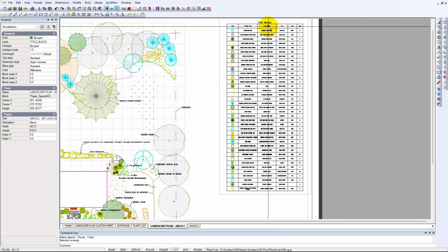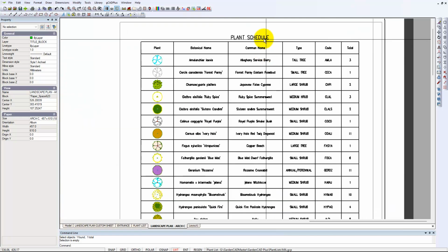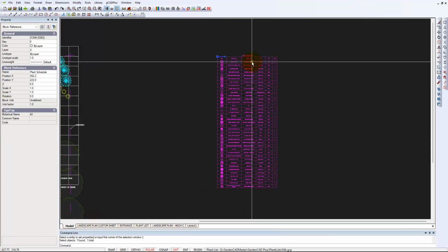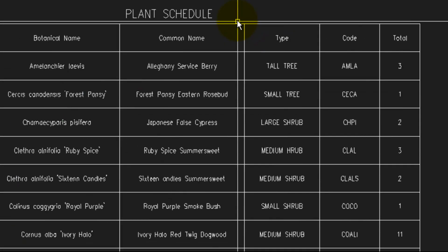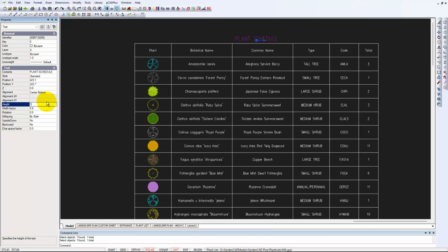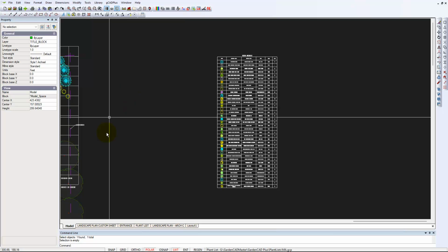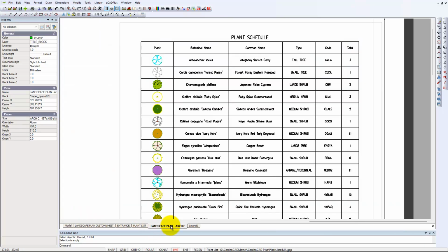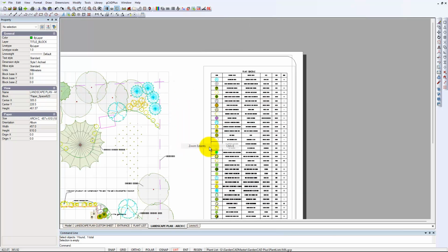If for the sake of argument, let me zoom in, and I'm getting distracted, we could dive in there by going back to modelspace. That's a block, and we can edit that block, and we want a larger typeface there. It's currently 1.0, so let's push it to 1.5, and the height of text jumps up, and we close the block editor and then jump back where we were, and now we've got a nicer looking heading. So zoom out and zoom extents.